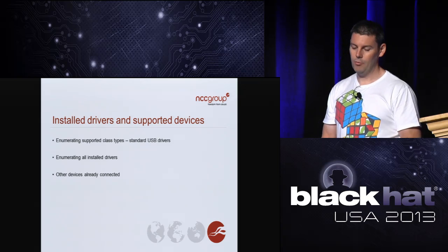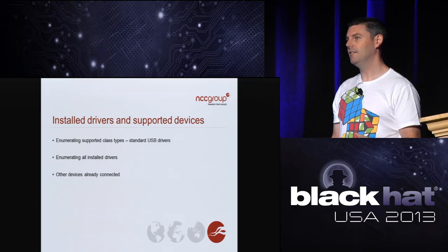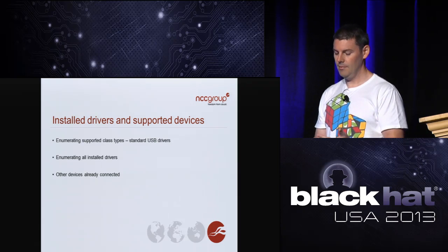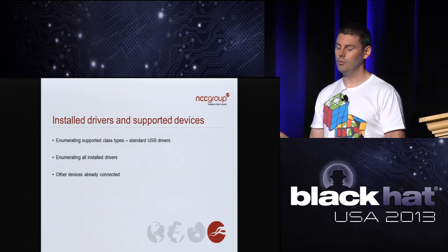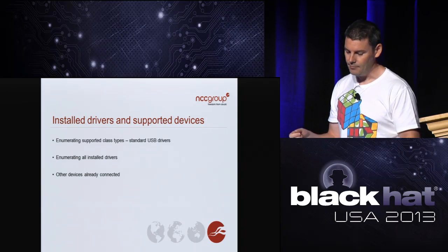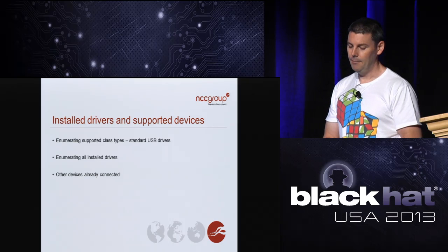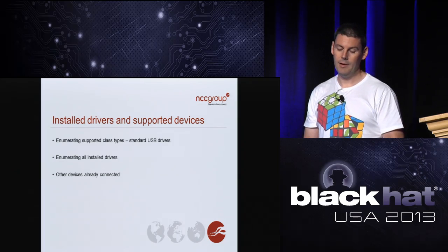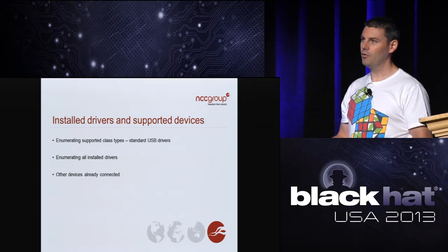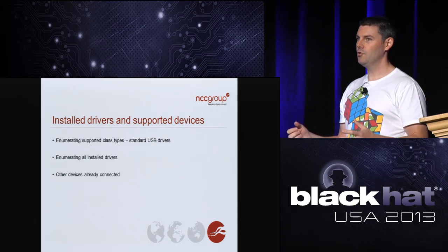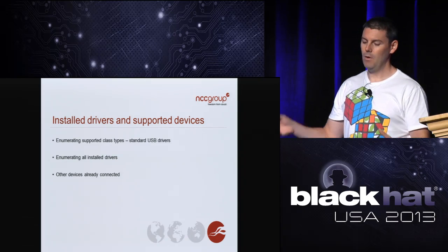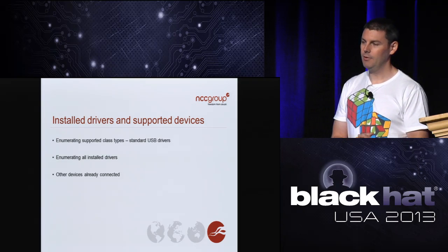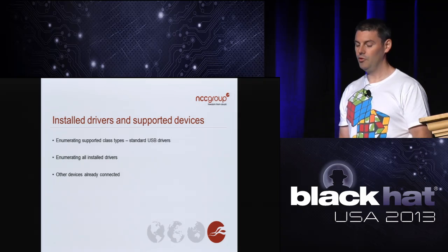Quite often in operating systems, a bunch of standard classes would be supported. So in Linux, for example, there's often a mass storage class, there's a HID class to control keyboard and mice, that kind of thing. And then there are more specific classes that you have to install separately. So if you've got an embedded system, a box that you've plugged into, before you start trying to work out if there are any particular implementation flaws, bugs within the way that the USB drivers have been implemented, you need to work out which ones you can test.